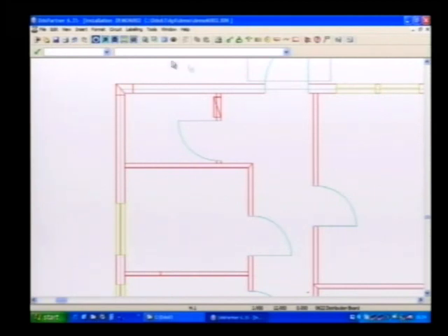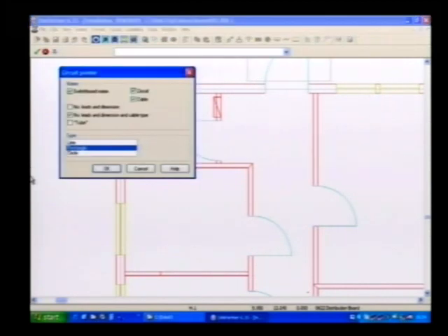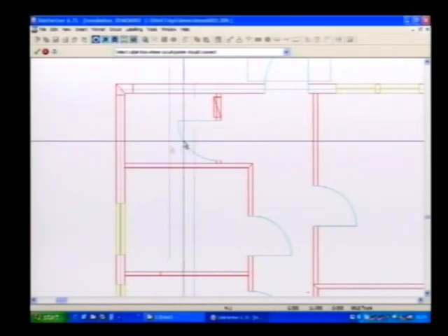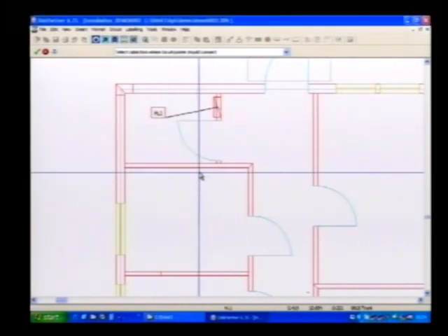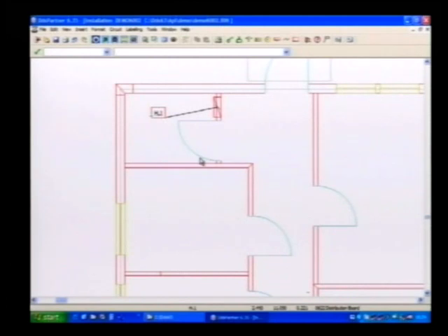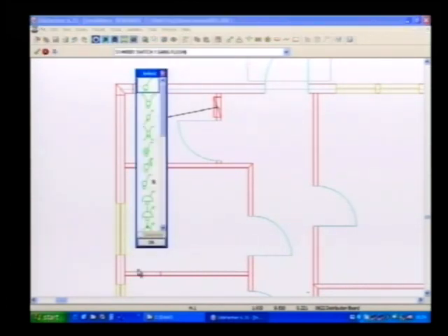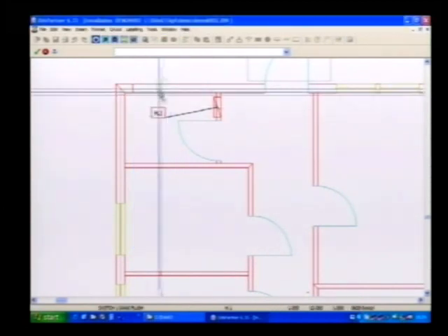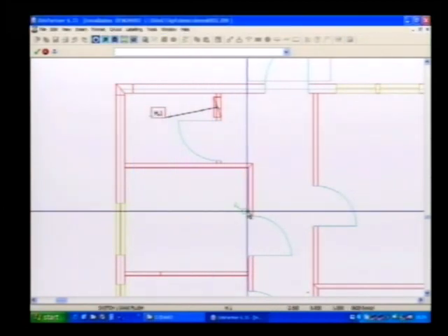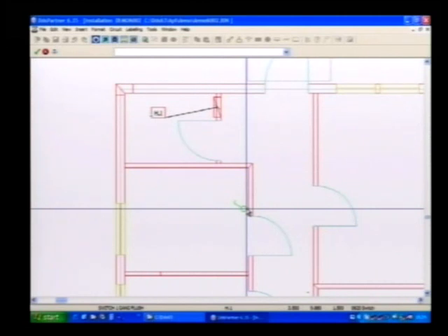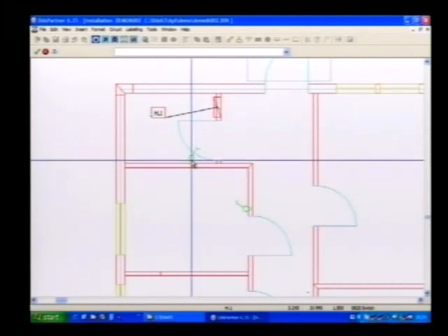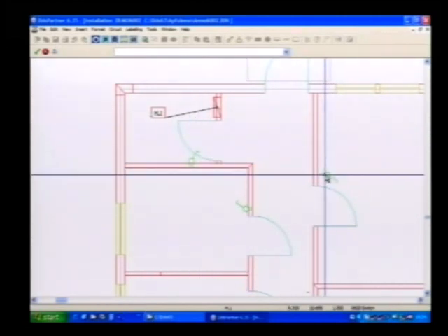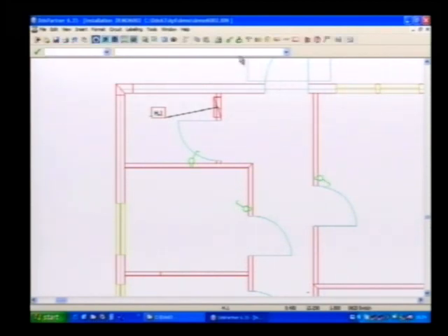Please continue. Yes, thanks. I continue with placing or defining first a new switchboard. I give it an identical name and place the symbol with the snap function into the wall. I can anytime place a circuit pointer. There could be many switchboards, so we have total control. Here it's H.1.